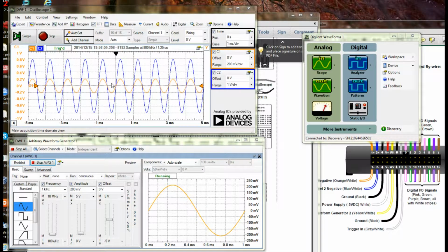So what controls scope triggering? There are 4 conditions here that control scope triggering. First is the mode between auto and normal. We'll talk about this in a second. The second is where we are getting the trigger source from. You typically only use channel 1 or channel 2. We're going to use channel 1.